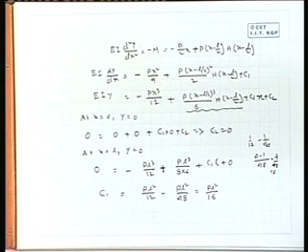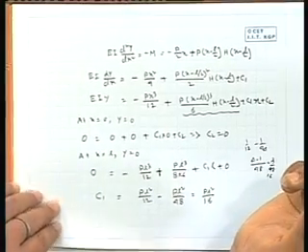Now, once we have the value C1 is equal to PL square by 16 and C2 is equal to 0, we have the expression of y, we have the expression for dy by dx, we can substitute and get the important values, say maximum deflection at the center of the beam, maximum slope at the supports. So, from here we can calculate all those quantities.